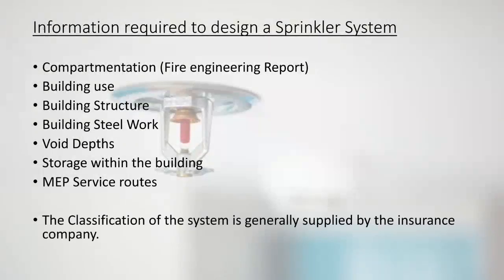The classification of the system is generally supplied by the insurance company. Because at the end of the day, the insurance company are there to pay the bill if the place burns down. So, as I say, the principal consultant should pick that. However, he should consult with the insurance company, which is in the main rules, BS EN 12845. It quite clearly states it should be initial consultation with the insurance company.